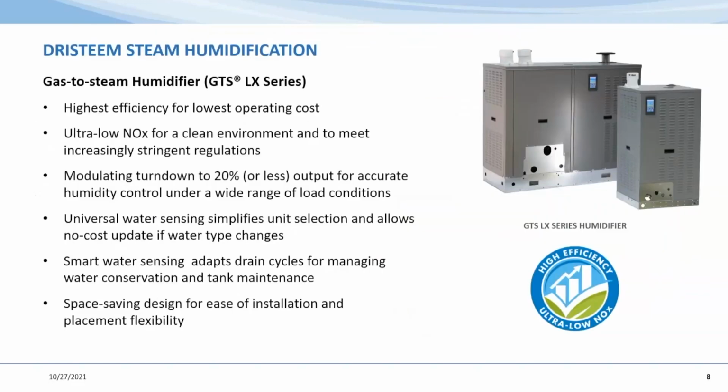Moving on to the next technology that DriSteem has to offer. Looking at our gas to steam humidifier LX series, this is the highest efficiency gas humidifier on the market. It also is low NOx to help meet those environmental and regulatory needs throughout the environment. Another great piece to this is it has that turn down ratio that's quite large for the industry, down to 20% or less, to give you that accurate control that we're talking about to help minimize overshooting of different humidity conditions.